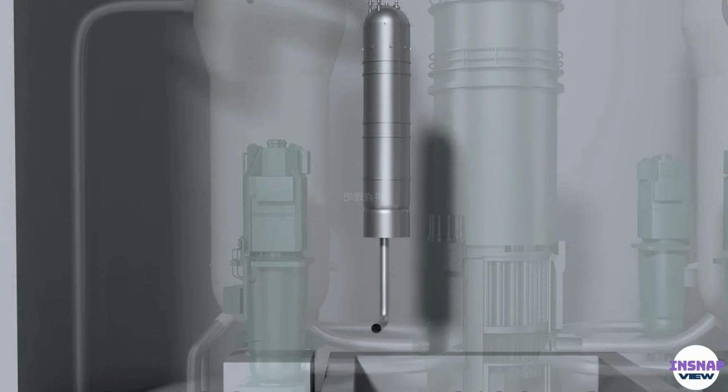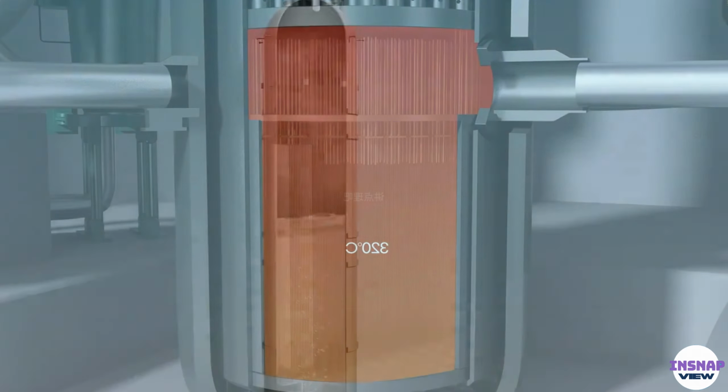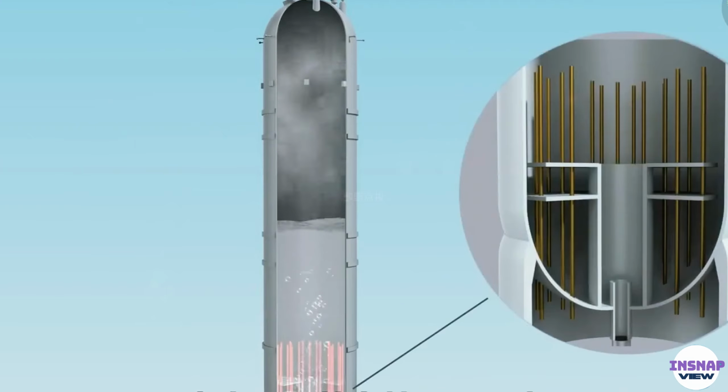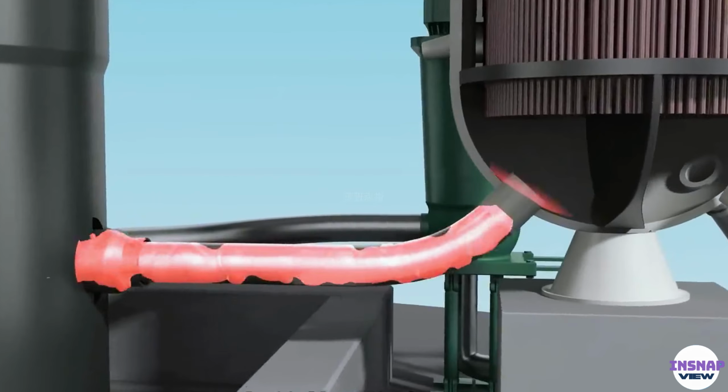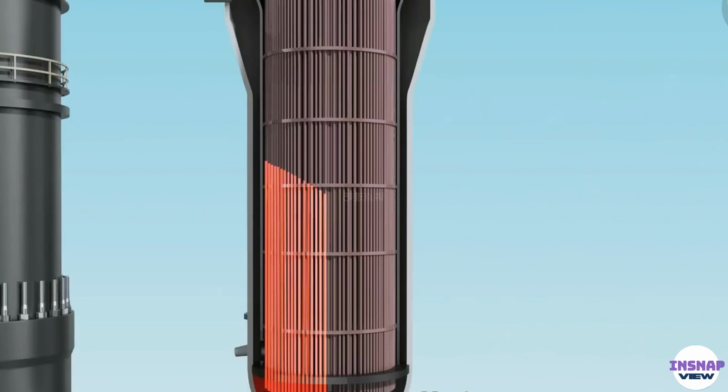It enters the steam generator. A pressurizer is connected in the middle. The pressurizer will increase the water pressure to 150 atmospheres. High pressure keeps water from boiling at high temperatures. The principle of a pressurizer is actually a high-pressure heating principle, increasing water pressure by generating steam pressure.